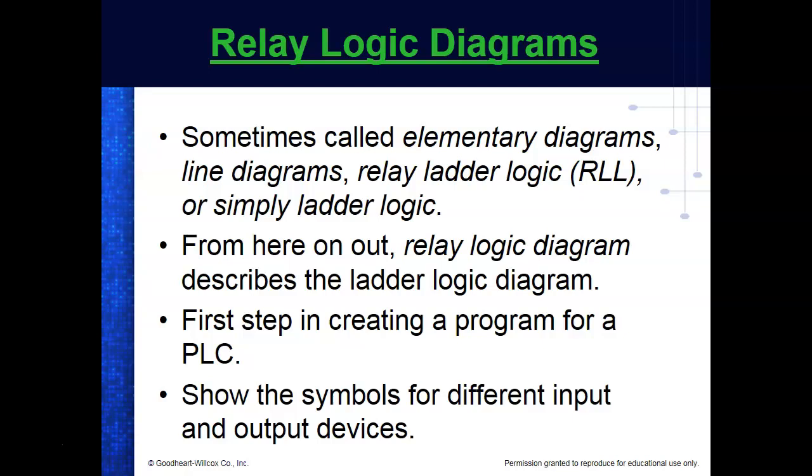Very seldom do we draw up all the relay logic and then take that relay logic that we spent all this time on and convert it over to a program. So normally what we do now is write the program according to what type of inputs we have and what type of things we're supposed to control.